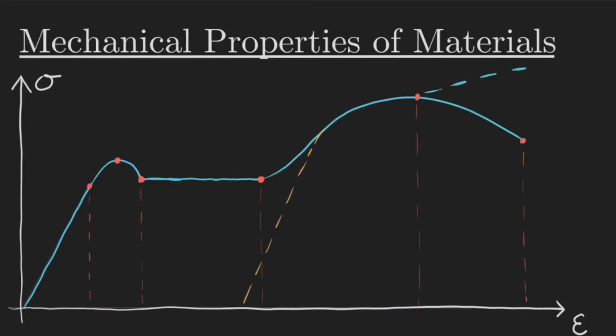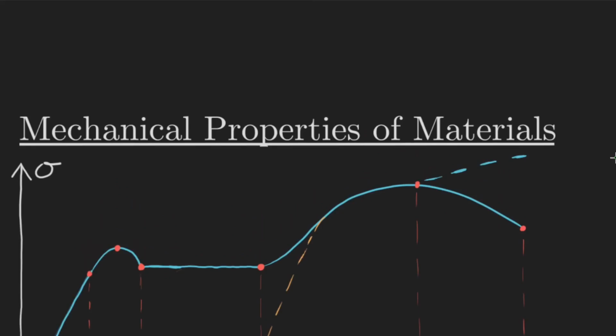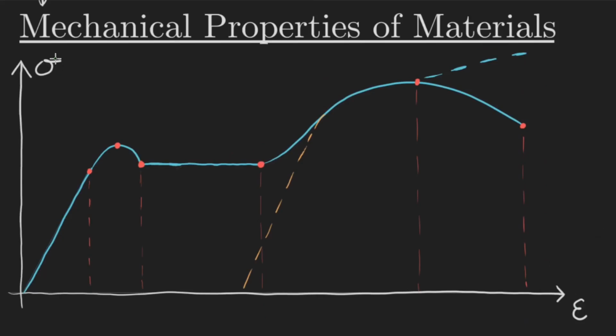Now, when you have some material, what you're usually going to do is something called a tension test. There's a bunch of data about different materials like steel or aluminum, whatever you happen to be using. Basically, they take a little slice of it and hook it up to these clamps, and then they increase the force more and more slowly until this thing fractures. And then what we get is a diagram of the strain and the stress. The stress applied is inferred based on how much force is being applied and the area.